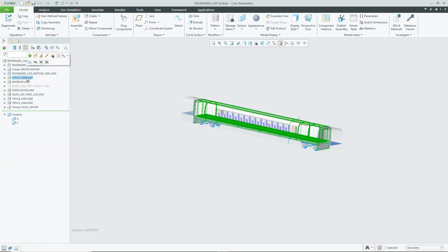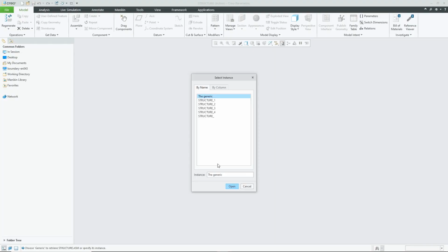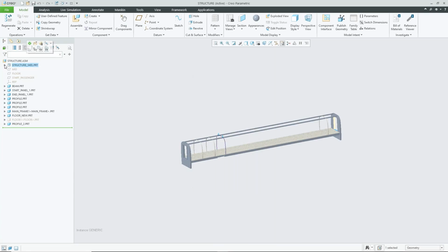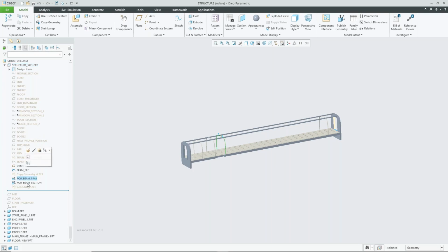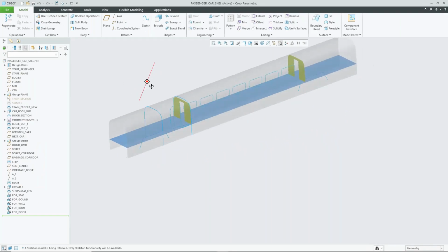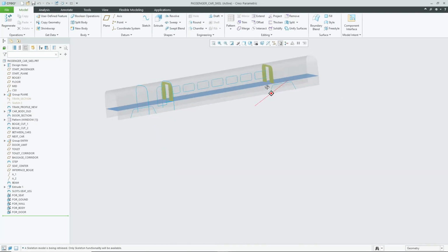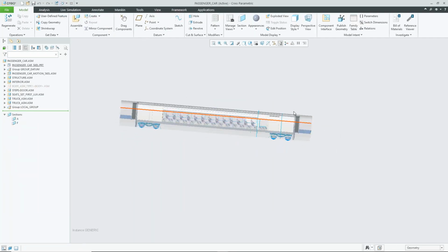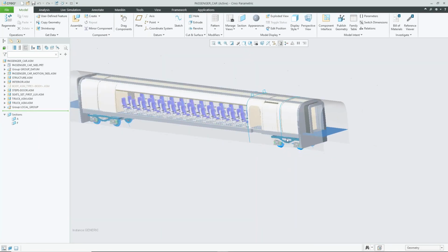So when we go back into here and we begin to look at these individual assemblies, one of the first things that it has is its skeleton model. And when you look in it, it actually has geometry copied from the original skeleton. And that's what we're looking at here. Now, I will show you this in a little bit more detail in just a little bit to show how we can copy geometry, but I'm just showing you the overview of this one right now. So we use the skeleton model to copy that geometry. And now when we begin to manipulate our features or our parts, we're going to use the geometry that we had from our skeleton model to properly develop our parts. So we'll just copy those inside of here.